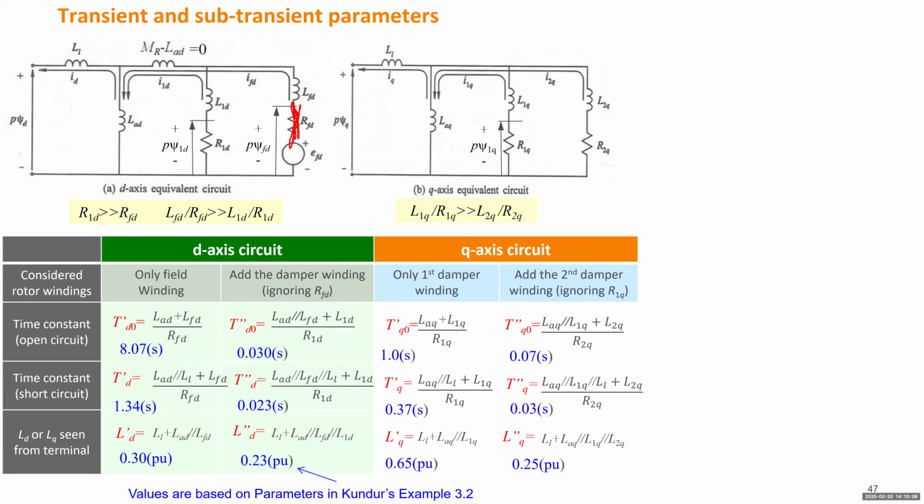If you remember the steady state value, I think we discussed at the beginning, when we calculated the delta I, do you remember what that XD is? It was 1 point something, right? Much bigger than this value. So you can tell, when you add some contingency, the inductance from the terminal suddenly decreases to this lower value, very different from the steady state value. That LD is about 1.5, but now it becomes 0.3.